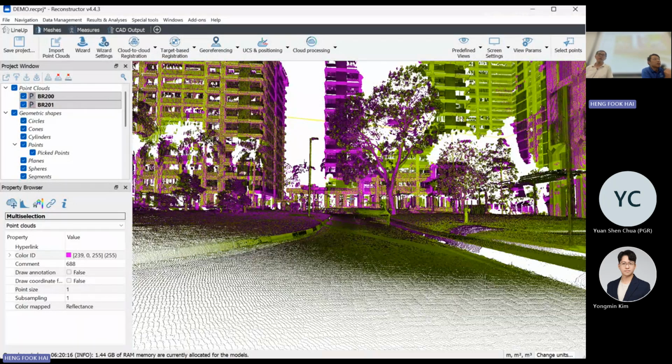And if you continue to do 3D scans for, say, the HDB estates, you could be looking at a good 50 or 60 scans, considering you have some blind spots, some corners that you're unable to scan. Later when you bring all this information back into the office for post-processing, it's pretty fast. You get the scan in a minute. But sometimes when you start to layer on layer and press the button, it could end up running for a long time.